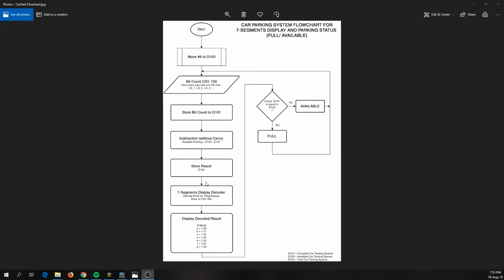So what it's gonna do is decode it for a 7-segment display. We have 4, put it inside the decoder. The decoder will automatically decode, like if you receive 1, then it's gonna show the 1 on the 7-segment display. This one is together with the Omron PLC, so you don't necessarily need to check the value; if this value, you should show this, it's automatic, which is quite nice.